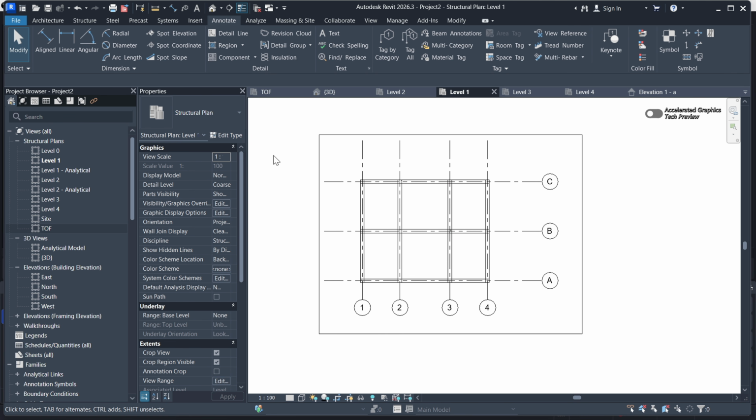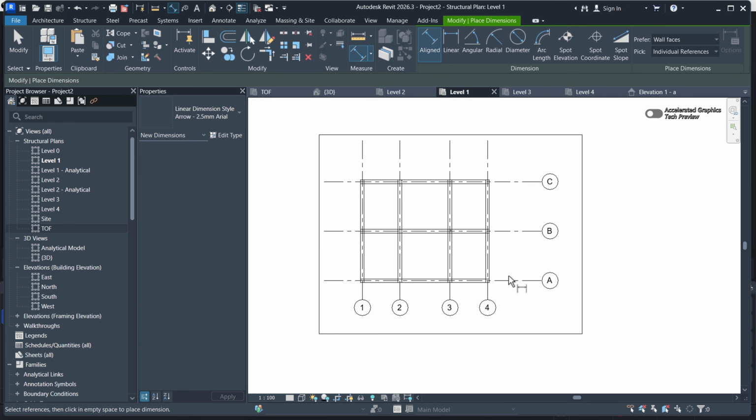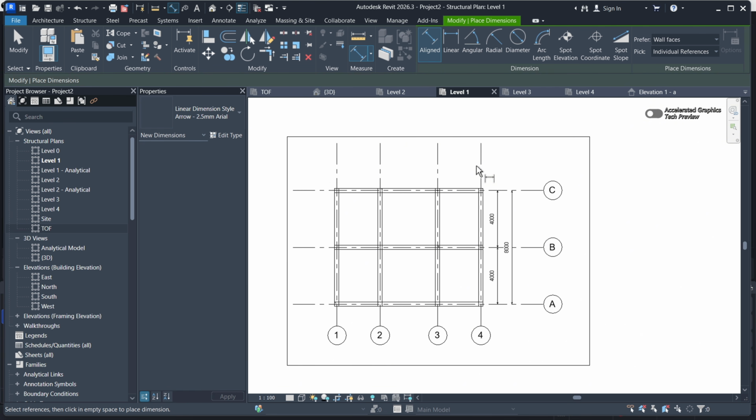Perfect. You can proceed with the dimensions, click on annotate, align dimensions, and just have those dimensions by just clicking and place it here. Then we can have the outer dimension if you want. You can see that it snaps like that so that you can perfectly space them there. Also this one, and continue like that. I'll start it here. The final one is going to snap right there and click.